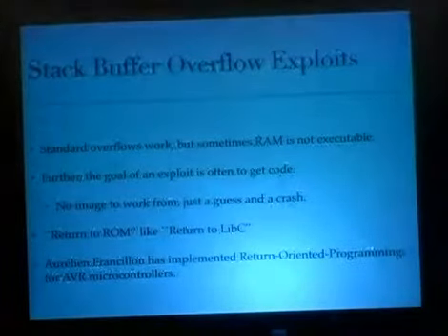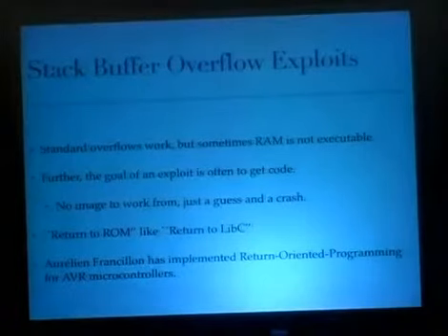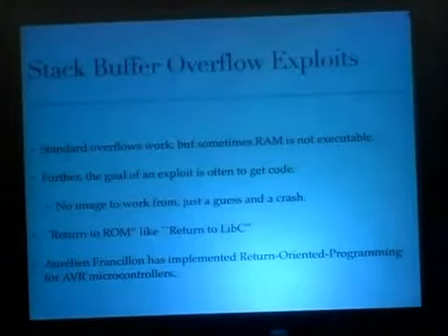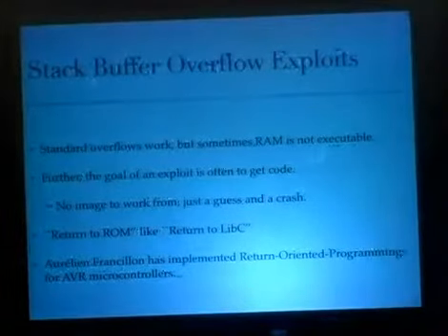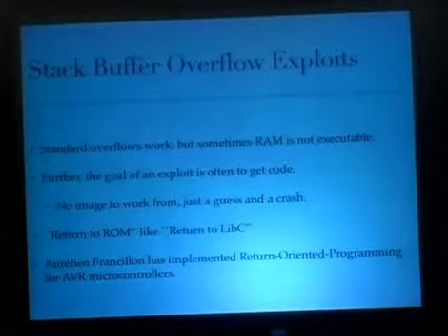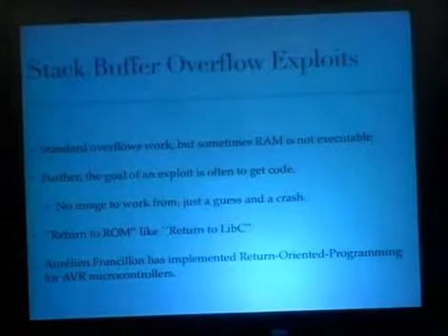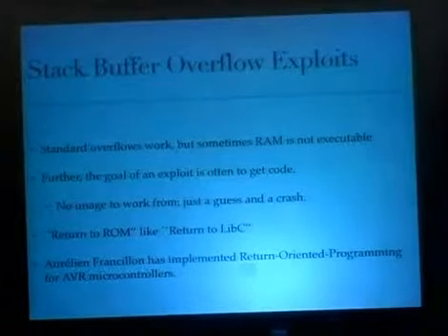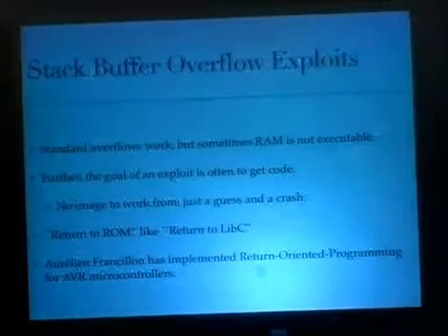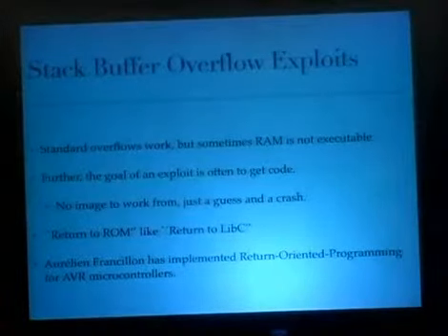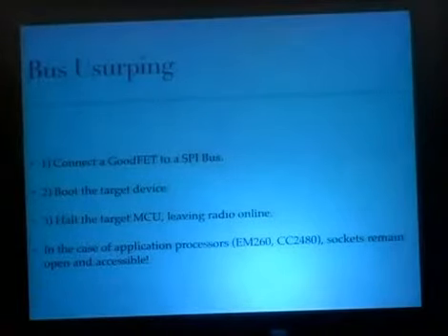And Aurélien Francione, a researcher that I've worked with who used to be in Grenoble but is now in Switzerland, he's implemented a complete return-oriented programming attack framework for these chips. So you can actually give it a firmware image and have it search through and find all of the gadgets necessary to move RAM into flash memory to later be executed, even though the chip does not allow the execution of RAM. It's quite a nice attack.